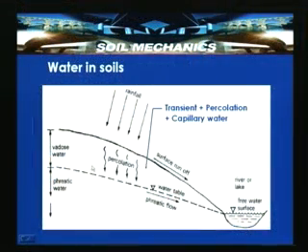So, here are different cases like water in soils. Generally, for a given terrain, the rainfall has a surface runoff and percolation; that is, whatever rainfall occurs, part of the water percolates and part undergoes surface runoff. The zone above the groundwater table is called the vadose zone or vadose water. This surface is also indicated as the water table or phreatic surface, where the pressure is atmospheric, that is 0. So, here is a free water surface.